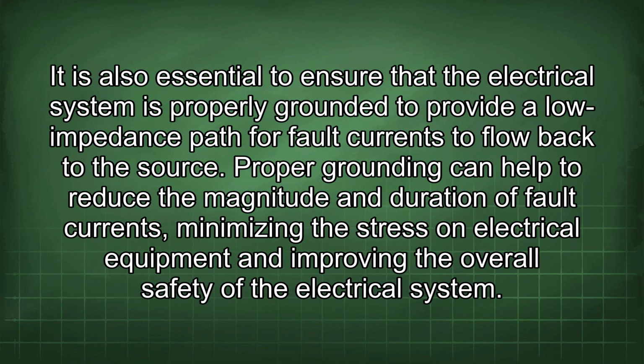It is also essential to ensure that the electrical system is properly grounded to provide a low impedance path for fault currents to flow back to the source. Proper grounding can help to reduce the magnitude and duration of fault currents, minimizing the stress on electrical equipment and improving the overall safety of the electrical system.